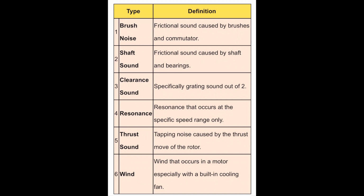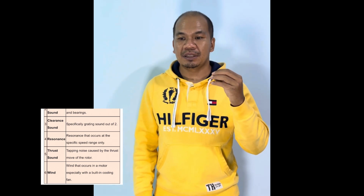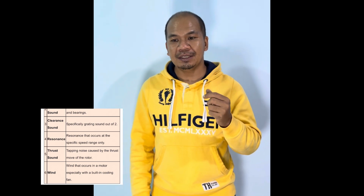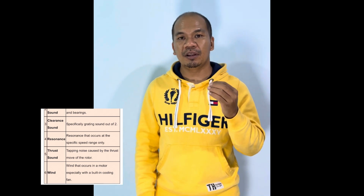The third one is clearance sound, specifically a grating sound out of tune. The fourth one is resonance. Resonance occurs at specific speeds and ranges only. And then we have thrust sound, a tapping noise caused by the thrust movement of the motor. And the last one is wind noise, which occurs in a motor especially with a built-in cooling fan.